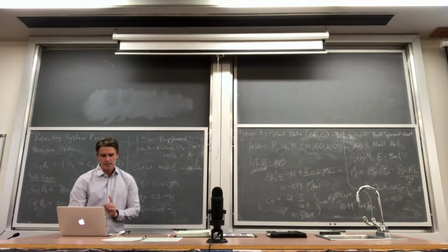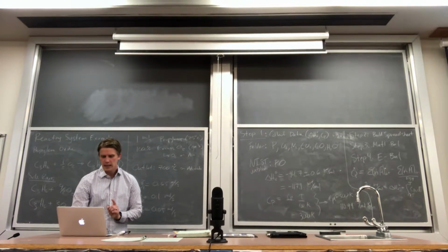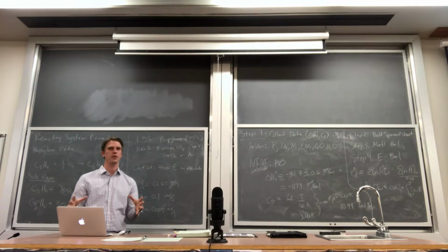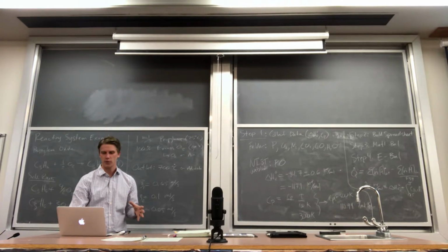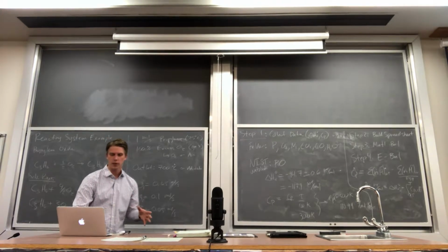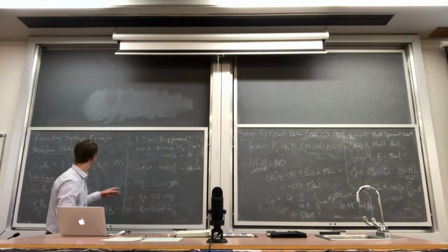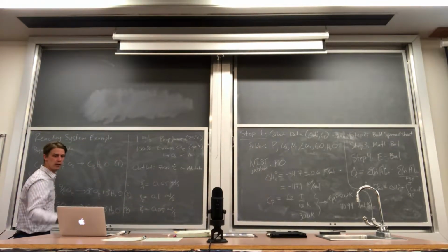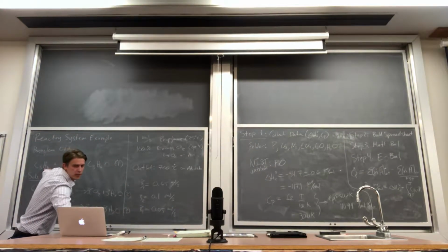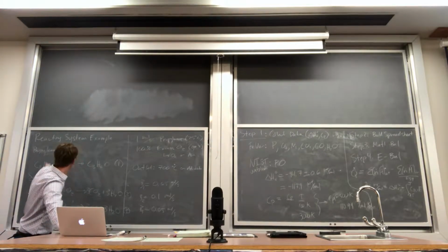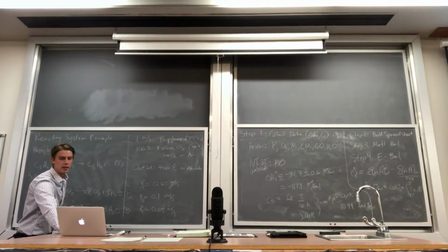So what I did is I entered in here all of the stoichiometric coefficients for all of the different reactions. So let's go through reaction 1 first. Stoichiometric coefficient for propylene is -1. I just entered a -1 when I was covering it up. For oxygen, it is -0.5, and for propylene oxide, it is 1.